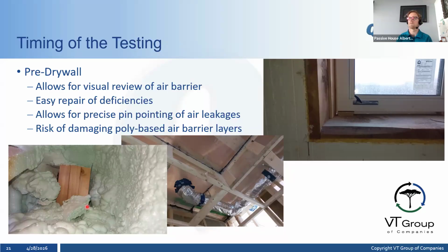Obviously, the thermal camera is most effective when we have a temperature difference between inside and outside. So right now we're entering the difficult time of year to do thermal imaging. Me and the team, we've got some processes in place to try and maximize the effectiveness of thermal imaging. But it is a really handy tool, and it's much more effective, I find, than filling the house with smoke and looking around on the outside.